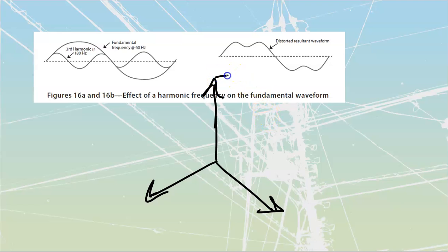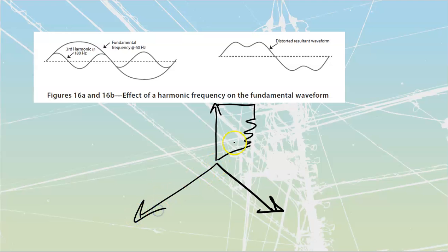And so if I take a single-phase load off of this and connect it back to the neutral over here, I'm going to have an additional amount of current going through there, IR, which means I'm going to have an additional amount of volts dropping across my source. In effect, the single-phase load connected across there skews this whole triangle so that it becomes shorter on one side, the side that's got the single-phase loads, and it maintains its length on the other two. You see how uneven this triangle looks as a result of these single-phase loads.